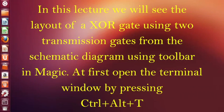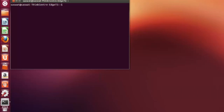In this lecture, we will see the layout of a two-input XOR gate using two transmission gates that is drawn from the transistor schematic by using the toolbar. In order to open the terminal window, press Ctrl Alt and T, then type magic, press enter.